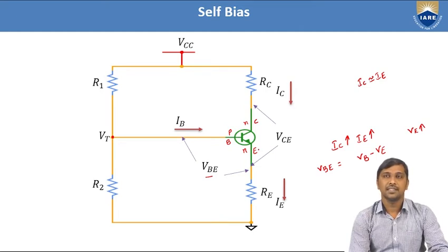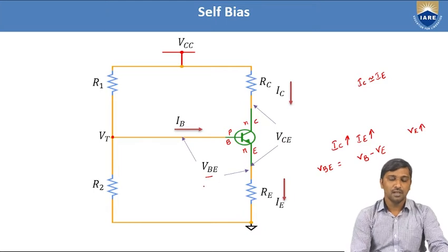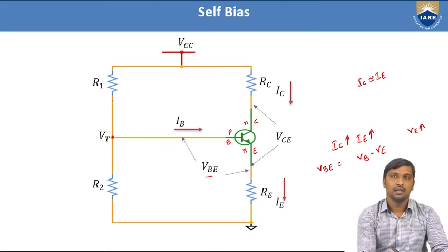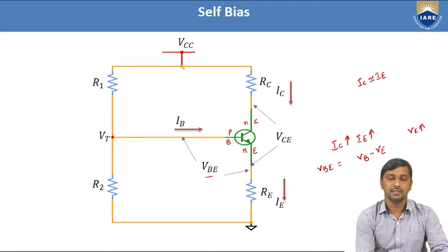If the transistor is in the active region, we can say that it acts as an amplifier. To satisfy this, we use a potential divider network made with two resistances, R1 and R2. This R1 and R2 is biased with VCC, which is of positive polarity.